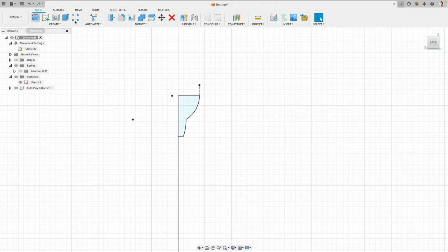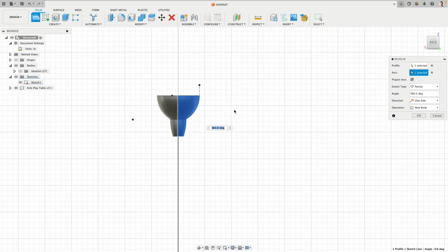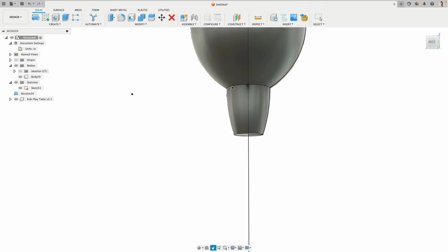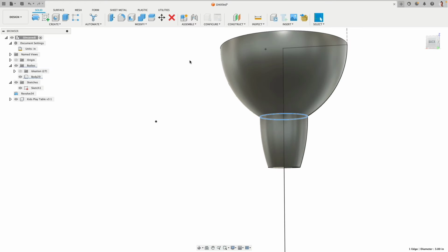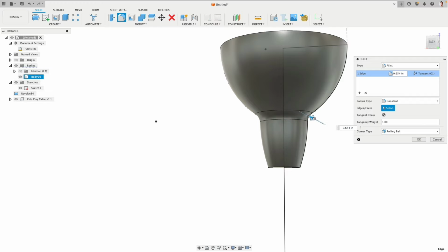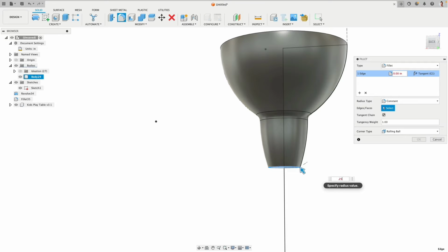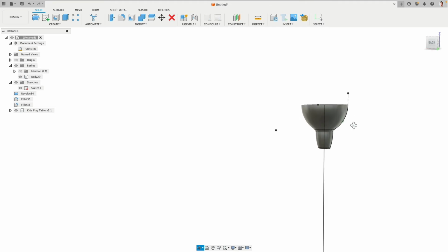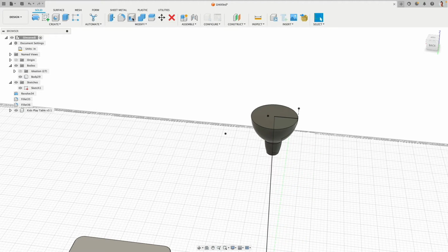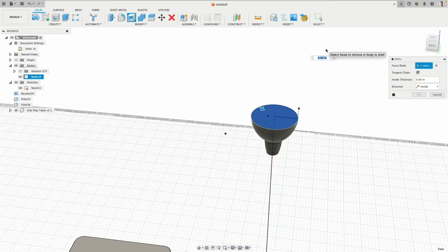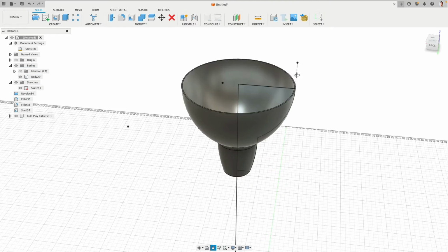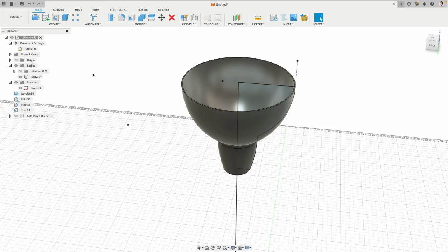So you revolve around this axis. Very nice. And then here we add a nice fillet. There we are, 0.5. Right click, repeat, and then here, 0.25. There we are, very good. And then we want to core this also out. Here, call this out. Let's say, yeah, it's not very thick, 2 millimeters. Yes, that's right. While my scene is working in inches, now you can type in any other unit.